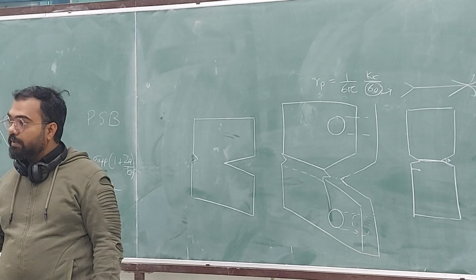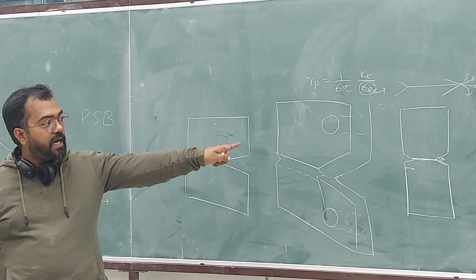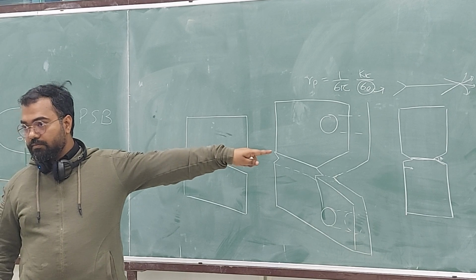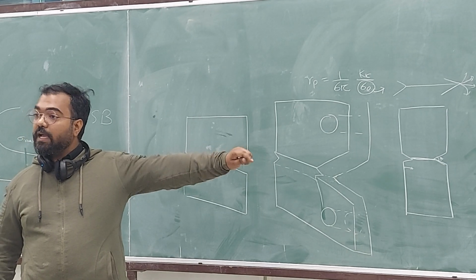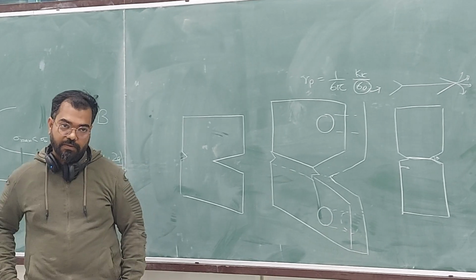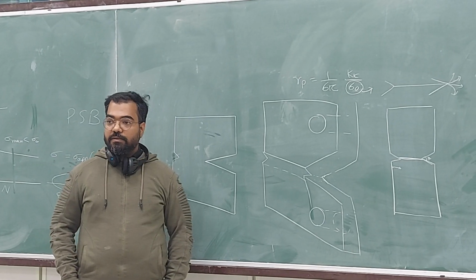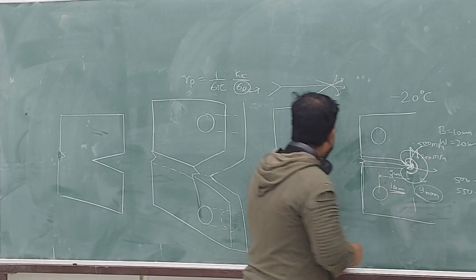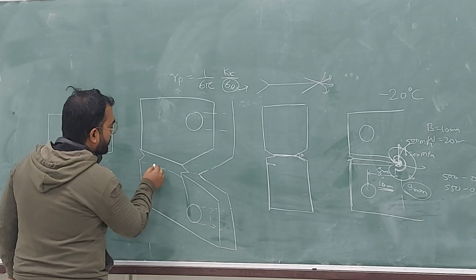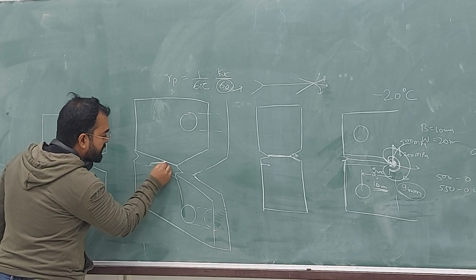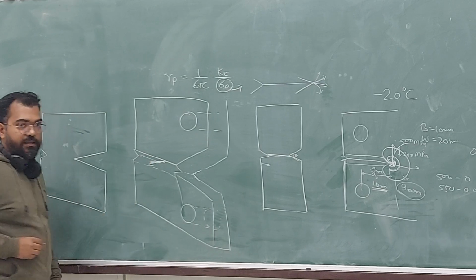Why 0.5? Because beyond 0.5, in that range, properties really don't change. What happens beyond 0.65 is a different game, and not much experimental data is there. Okay? So as I said, beyond 0.6, suppose your crack front is here, then this dimension and this dimension will become equivalent.